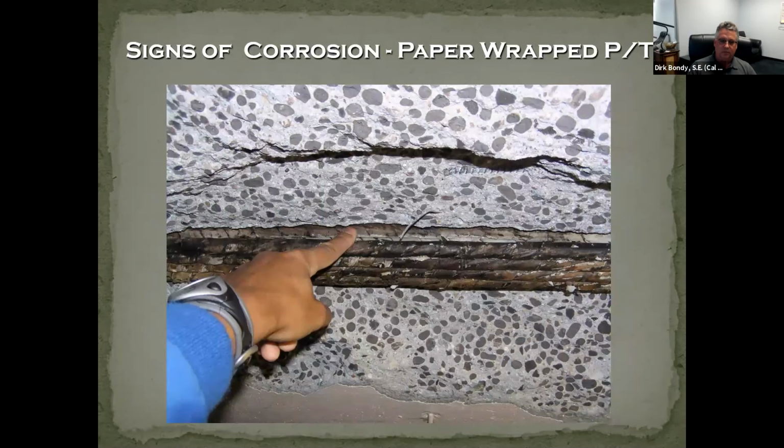Now, this is post-tensioning being moved by your finger. Now, if you've ever actually touched stressed post-tensioning, which I have because we do a lot of external post-tensioning, you can't move or budge that steel. But if you can move it with your finger, if you can move it with a screwdriver, if you can move it with anything, then it's not stressed. And that's how you know.